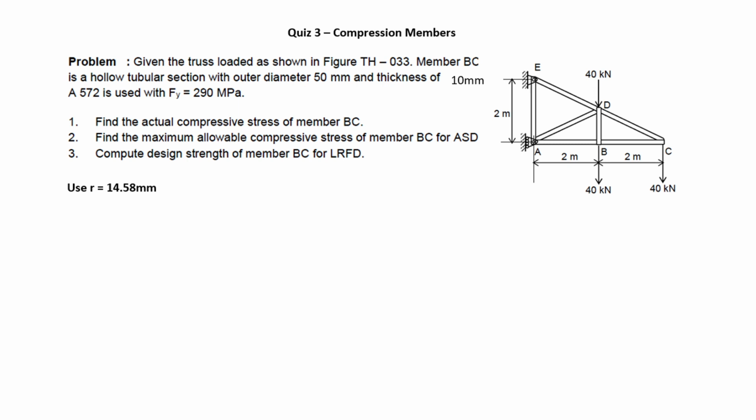And we have Fy 290. Okay, and then we're asked to find the following: find the actual compressive stress of member BC, find the allowable compressive stress of BC in ASD, and the design strength of member BC for LRFD.